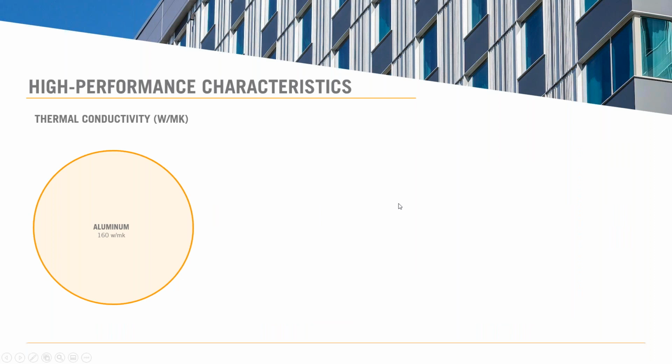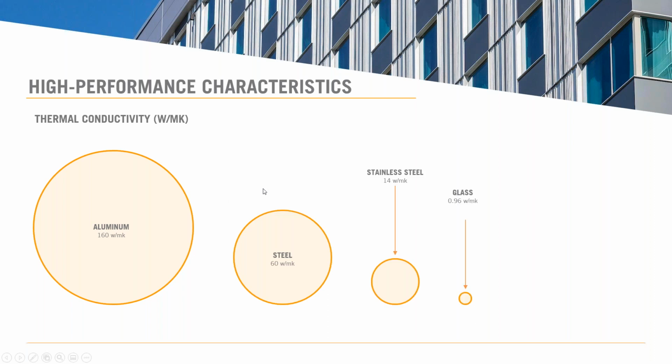The next characteristic, which is key to window thermal performance, is of course conductivity. Think of these circles I'm showing you as the holes in your bucket. You've got aluminum, steel, stainless, glass, PVC, fiberglass, and wood. Naturally, PVC, fiberglass, all these low conductivity materials are going to have a conductivity that's about 1,000 times lower than aluminum. So aluminum windows are fighting that in their design.